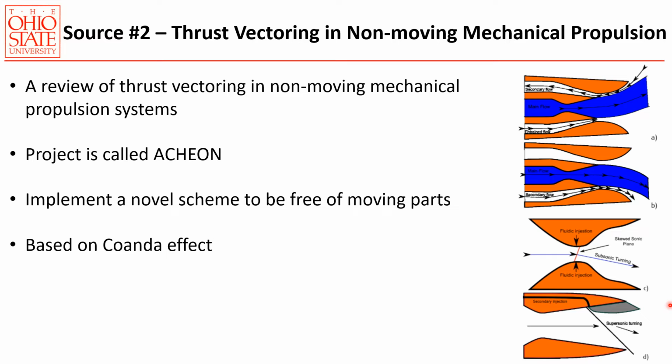The throat shifting control system is based on a converging diverging nozzle. Initially, the shock at the throat is a normal shock, but by applying a fluidic injection before the flow becomes supersonic, the shape of the post-throat shock is skewed without significant loss of thrust performance. The application of the injection in the subsonic region implies that the losses are minor, thus making the system one of the most promising ones from the point of view of thrust efficiency.